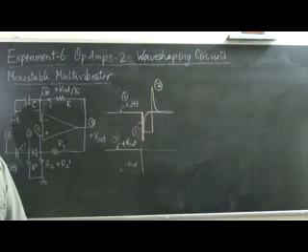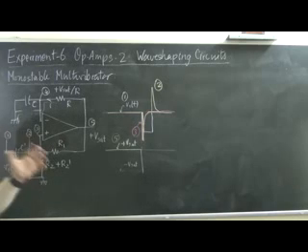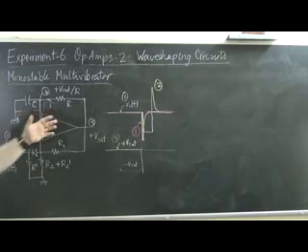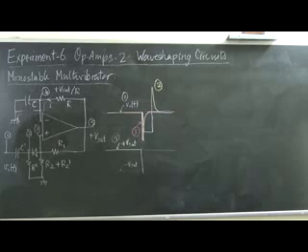And as the capacitor charges, a point is reached when its voltage crosses the voltage of the positive side. That time that the capacitor takes to charge over to the other side is determined by the values of R and C.